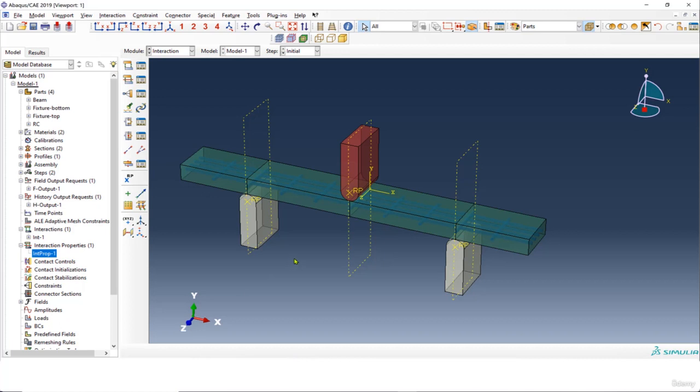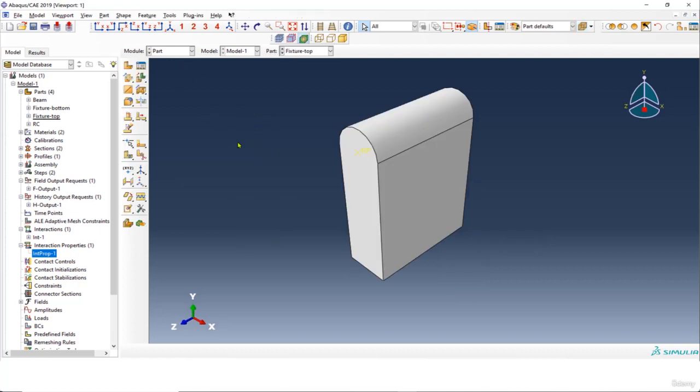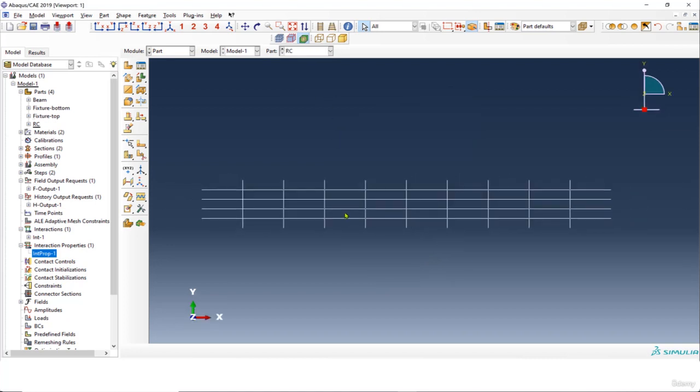Before doing that, I have to create some sort of set, because for me to select the inside of that beam, which is the reinforcement, it's difficult to do it like here. I would have to get rid of this corner and then select the reinforcement. To make your life easier, especially for complex geometries, I can create a set, so I can access the reinforcement much more easily.